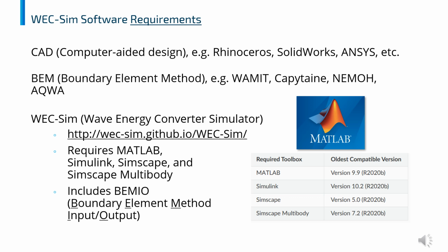Next, users will need a boundary element method solver to solve for the hydrodynamic coefficients. We support WAMIT, Capytaine, NEMOH, and AQWA boundary element method solvers. Lastly, since WEC-Sim is built on a MATLAB Simulink framework, we require MATLAB Simulink Simscape Multibody. We also provide a boundary element method input-output parser called BEMIO.